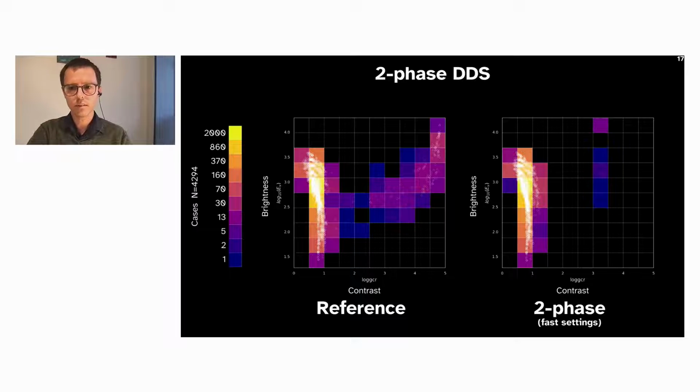At high image resolution and high accuracy rendering parameters, the 2-phase method can also match the distribution generated by the reference method. But tuning the parameters to generate results in a comparable time to the ray traverse simulation reveals that a uniform sampling approach breaks down, and it becomes impossible to reproduce the defining characteristics of the temporal daylight distribution.